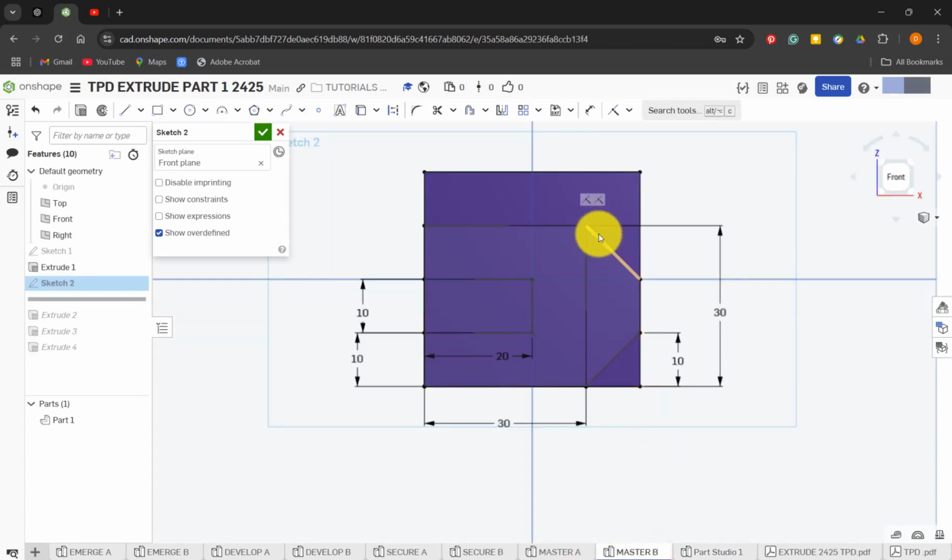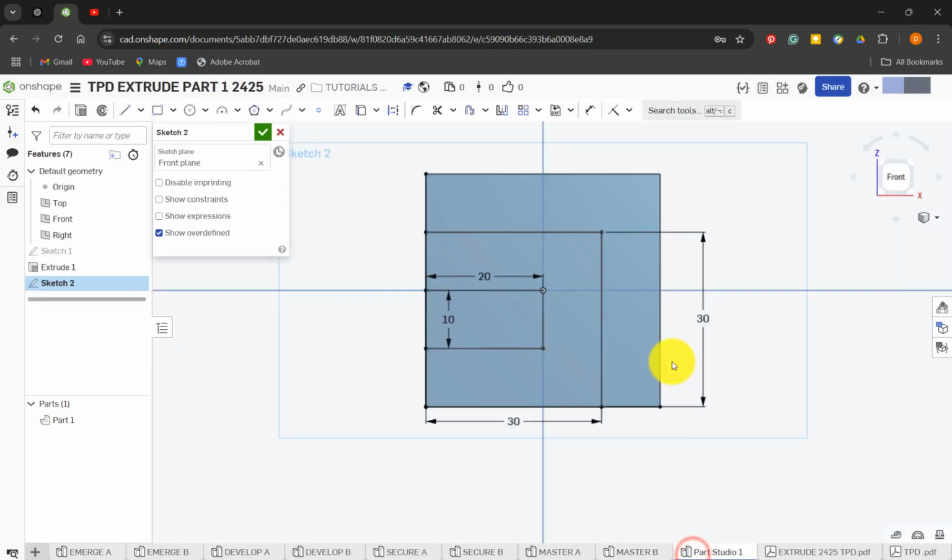And then the last little bit is to draw this diagonal down, coming to the centre, along the centre plane there and along here. So it's 10 millimeters along each one. So that's quite simple to do. We're going to go L for line, drag that down. I could wake this up, so therefore I can snap to that point there, and then come down and then go down again. And then this time, D for dimension, click on those 2 points, 10, click on that point,